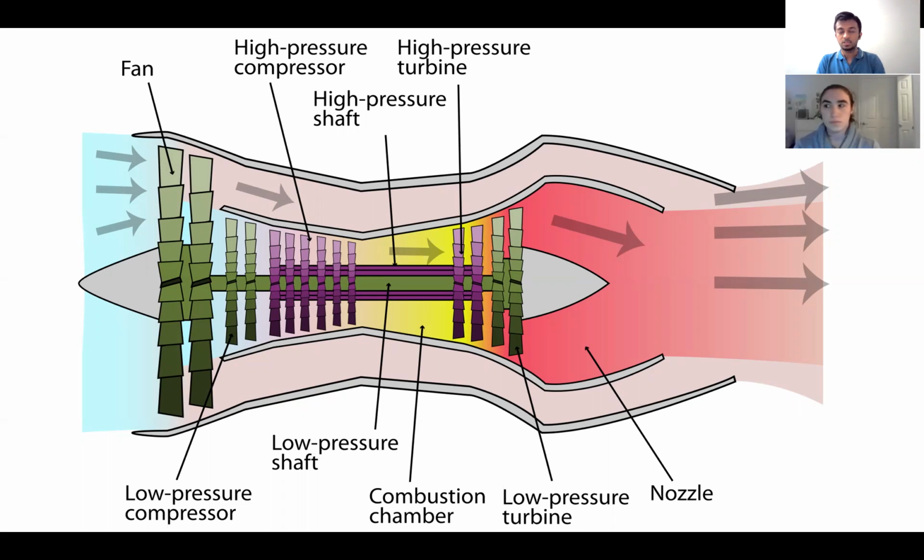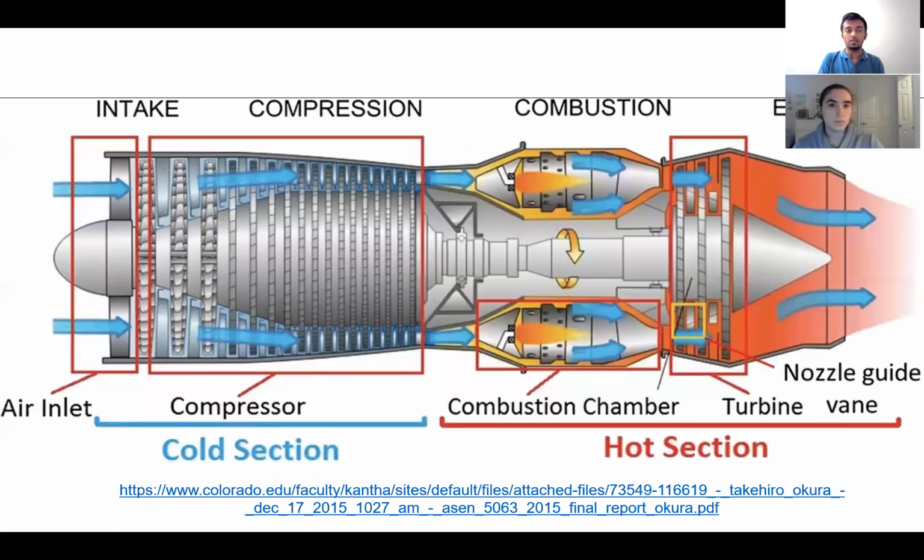The combustion chamber is a place where you require materials which will sustain high fatigue strength, which have high creep resistance, and which will live up to the expectations of high temperatures generated in that portion of the engine. And then you've got another variant of this engine called the turbojet engine, which has huge compression ratios. Again, in the combustion section as well as the turbines, they face the same dilemma and require the same properties as in the turbofan engine.